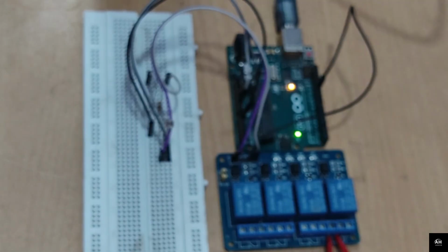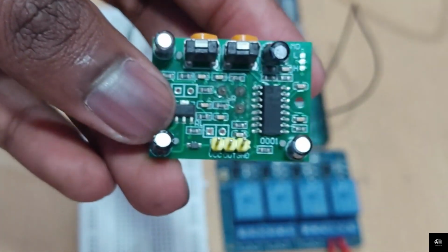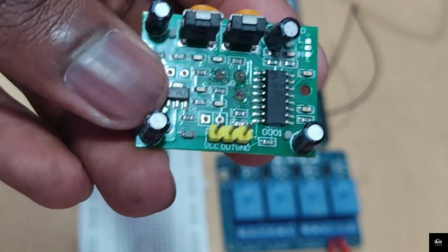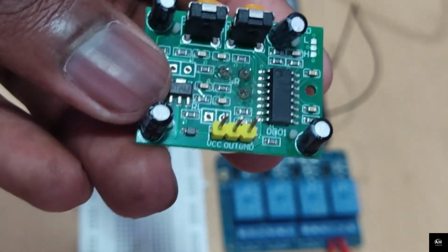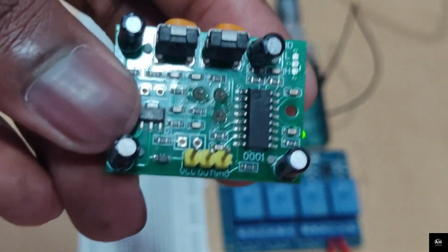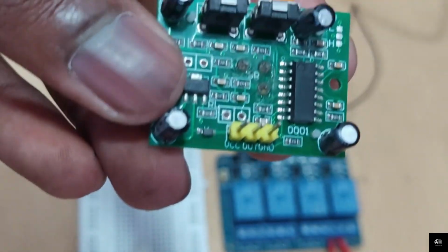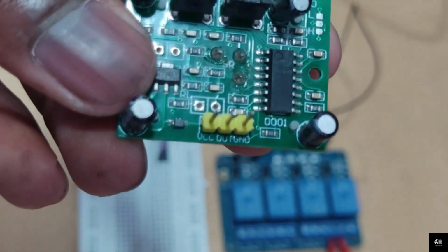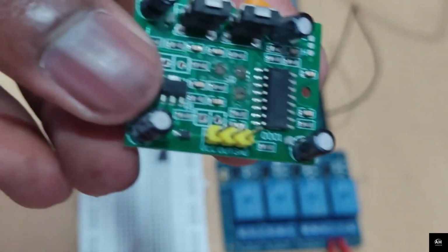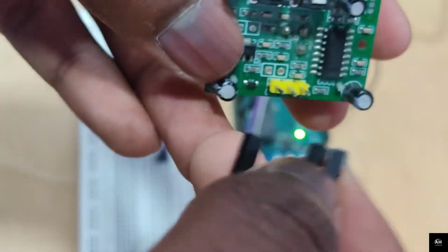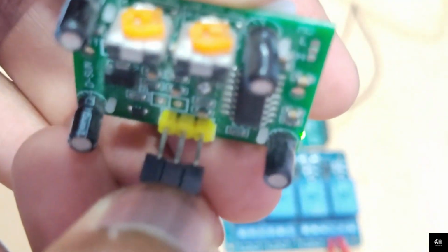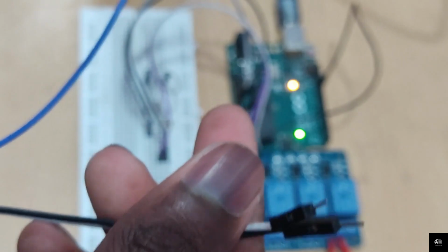So for that, first of all, we need to connect it with our Arduino board. So we will just connect this PIR sensor with our Arduino board. You can see here are the 3 pins on the PIR sensor. The first one is the 5 volt, the second one is the digital in, and the third one is the ground. So we will just connect some jumper cables with it. Here are the jumper wires, and we will insert these jumper wires with our PIR sensor. And once we are connected, we'll just connect them on our Arduino board.